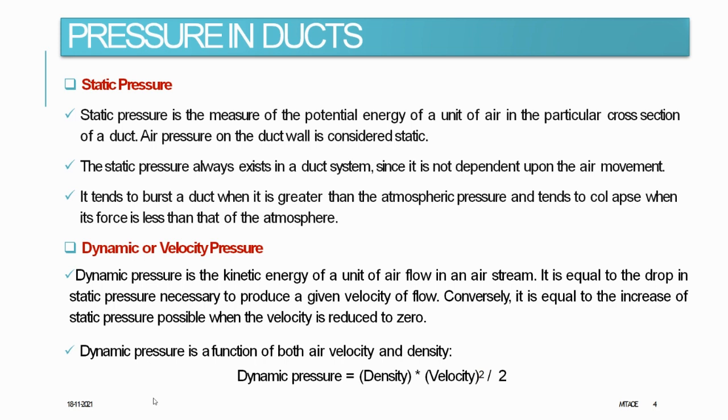So now in the static pressure, it tends to burst a duct when it is greater than the atmospheric pressure, and tends to collapse when the force is less than that of atmospheric pressure. So static pressure should be maintained in the range of atmospheric pressure to get a particular application done. So now moving towards the dynamic pressure or velocity pressure.